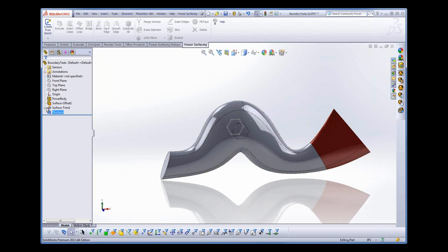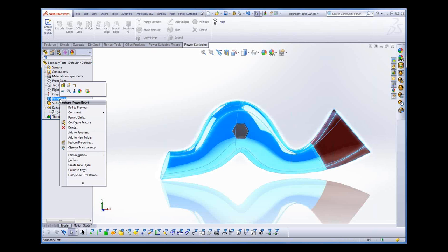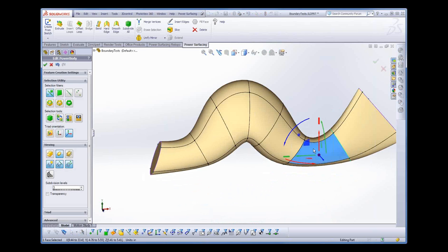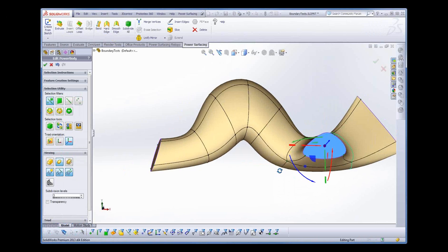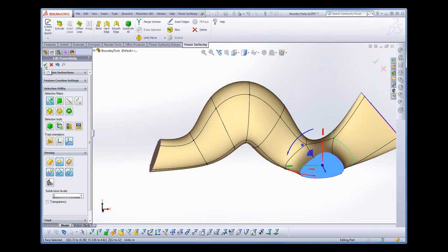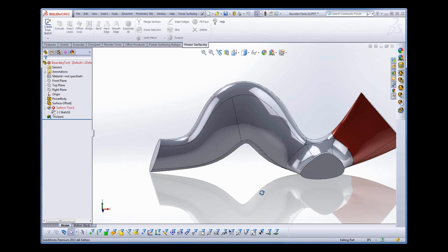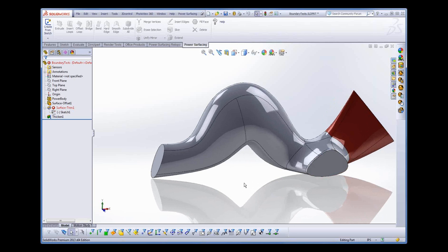So what's going to happen is when I go back, and if I change something, let me hide this for a minute. When I go back into the power body and make a change, you're going to see something happen. And this is one of the important things about boundaries. So I'm going to go back into edit mode. And if I disrupt the face count or the face numbering that happens internally by doing something silly like an offset and maybe a wedge edge weight there. If I now convert this guy, what happens is our offset and our trim actually got moved over here because that's where it thought that face was. So to avoid that, what we want to do is define a face to use for the surface in the first place.